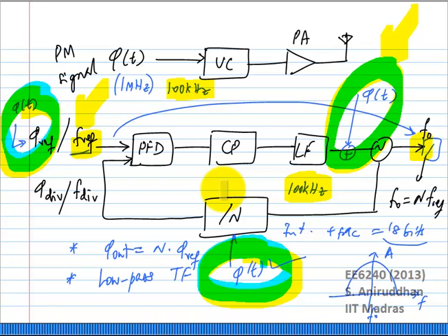The third thing is, even though we talked about 1 megahertz signals, most modern signals are not restricted to 1 megahertz. If you look at the original GSM signal, it had 100 kilohertz. Okay? And the original Bluetooth signal, which we gave as an example, also had something like this. So they were all very, very narrow band signals, purely phase modulated narrow band signals. This kind of transmitter worked really well. Okay?